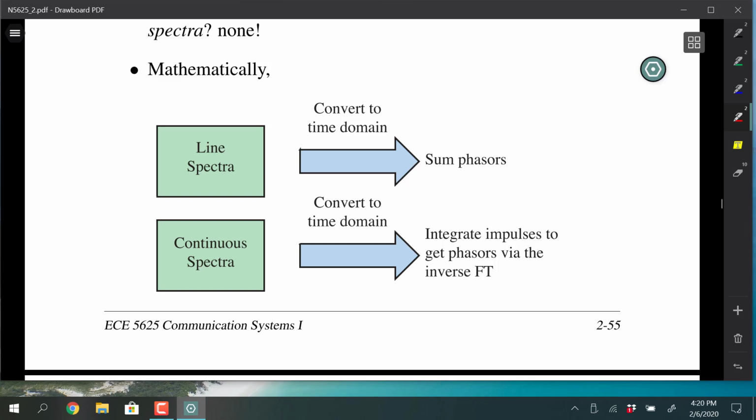And when the two signals are the same frequency, we come out of that multiplier, and this is where mixing action comes into play. We're going to get a difference frequency at 0 hertz, and that goes processing through a video amplifier, a narrowband low-pass filtering amplifier, and then we can have an envelope detector on that to get the energy or the power, through a diode envelope detector, in that signal that gets converted to 0 hertz. The sum frequency is eliminated when we do cosine times cosine. We get cosine sum, cosine difference.